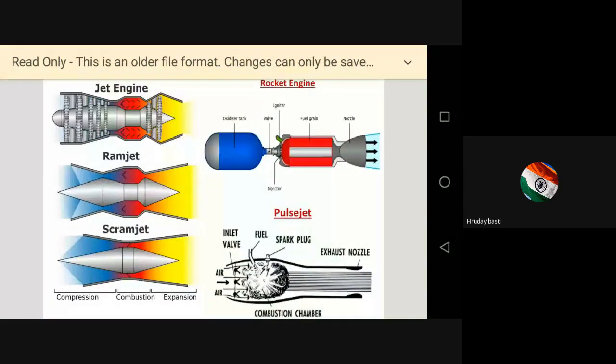Now last, coming to the scramjet engine, here we may have only the compressor stage, where we have the diffuser type of model. So we have only the diffuser, which is going to convert that supersonic speed of air nearly to subsonic, because it's not always possible to compress up to subsonic speed.